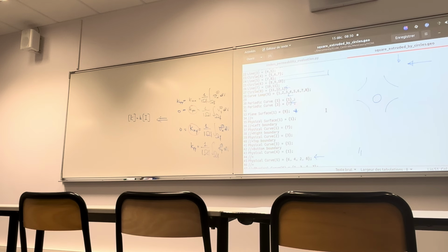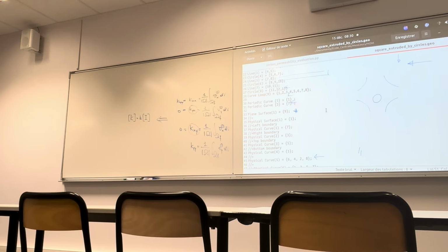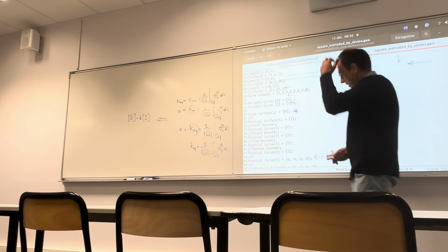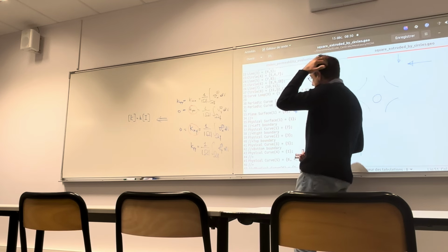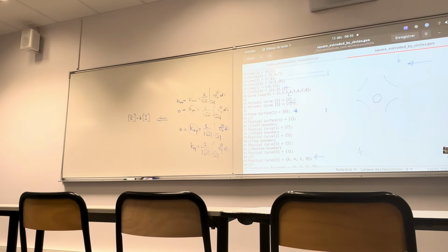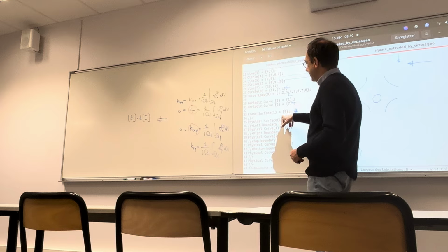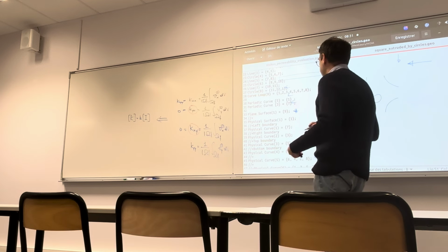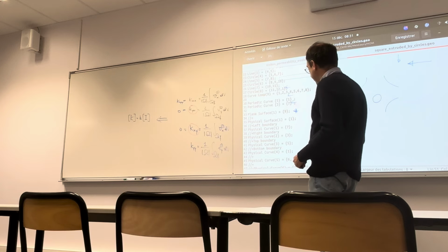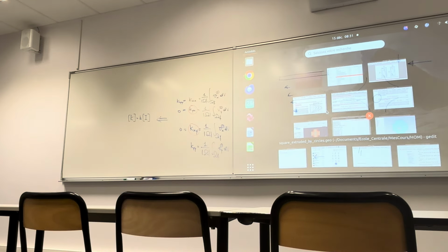It's quite simple if you look at the documentation of GMSH on how to generate an extruded region. I think, if I remember well, you just have to put here the second closed curve, the circle in this case. So essentially the idea is that if you modify here the definition of the plane surface and there the definition of the physical curve 5, then everything should be ready.